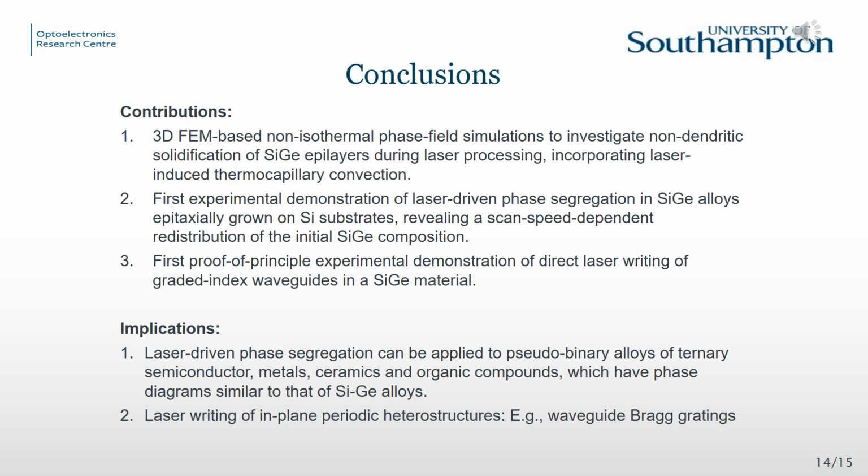As a conclusion, I would like to stress on the contribution of our work and its implications. We conducted 3D finite element method-based non-isothermal phase field simulations to investigate solidification of silicon germanium epilayers during laser processing, incorporating laser-induced thermocapillary convection. For the first time, we demonstrated laser-driven phase segregation in silicon germanium thin films epitaxially grown on planar silicon substrates. It enables on-chip post-deposition local tailoring of composition in silicon germanium thin films, which can be used to produce graded index waveguides with tunable compositional profiles.